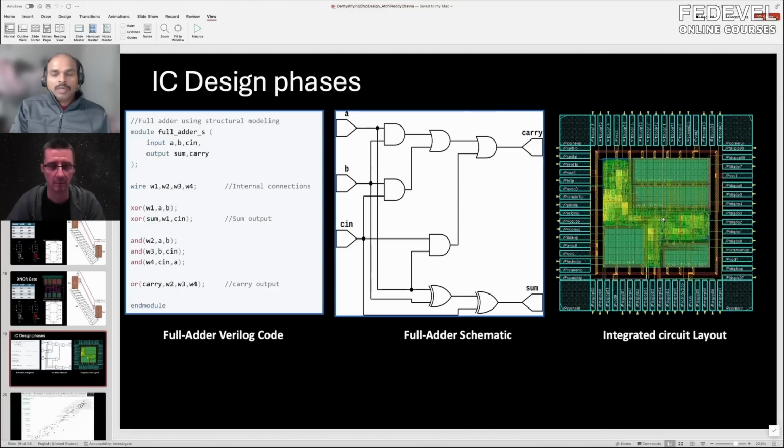The logic in the middle is digital logic that can operate at lower voltages, like 0.75. The lower the voltage, the less power it consumes, so you have an advantage there. However, on the periphery, with the signals that we receive from the external world, we have some dedicated interfaces, and they come with their own voltages like 1.2 volt, 1.8 volt, 3.3 volt signal levels. We cannot change those because those are the standards.